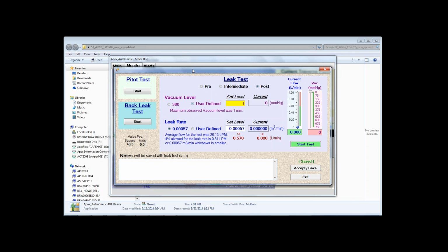I know it's in the EPA documents. Usually it's a 1 hour test if it's just for particulates. Now, if it's a really clean source, you may need to sample longer. Or if you're sampling for metals or dioxins, you may need to sample longer so that you collect enough sample that you can measure it. You may have to consult with the laboratory to determine how long you really need to sample.